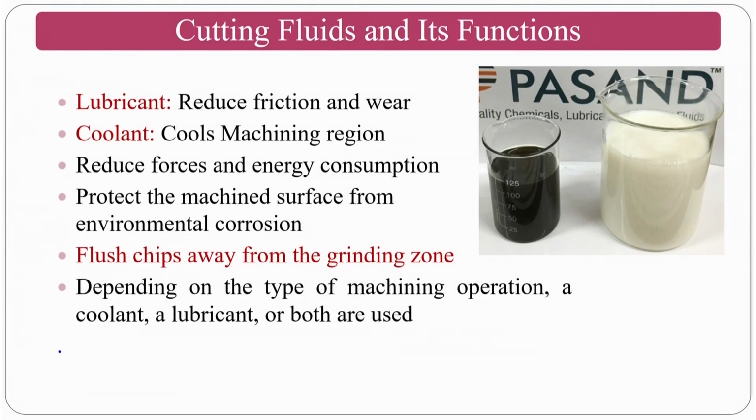So, cutting fluids and their functions. Basically, the cutting fluid's major function in this particular grinding process is lubrication, because abrasion is the main mechanism of material removal. So, to counter it, one needs a lubricating property. The second one is the cooling property. Temperature is generated, so in order to remove that, you need a cooling property. Reduces the force. Obviously, if it acts as a lubricant and coolant, then it will reduce the forces and the energy consumption that is required. Protects the machined surface from environmental corrosion.